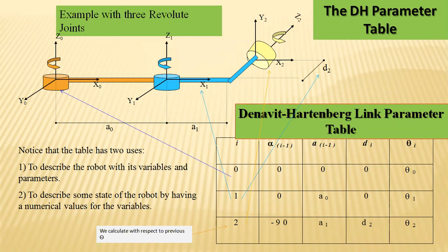In the first step, there are three prismatic joints, that is P, P, P. So only sliding joints will be taking place, hence it is not suitable with our example. Here it is clearly mentioned that only three revolute joints are existing. The second condition is the cylindrical or spherical coordinate system.